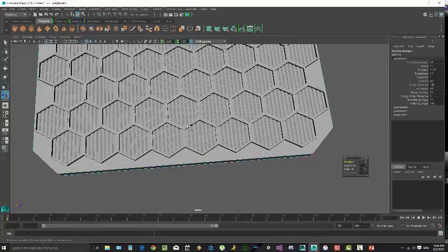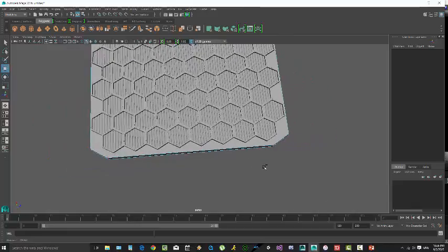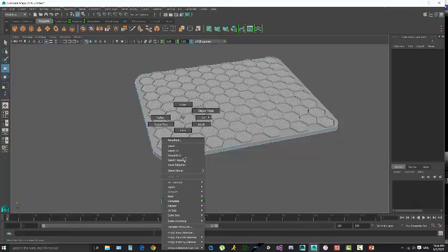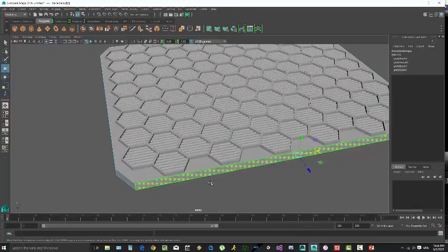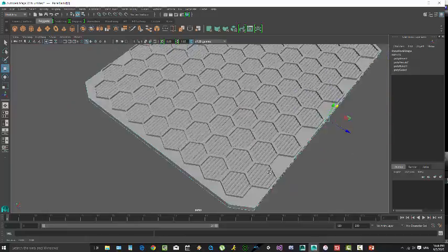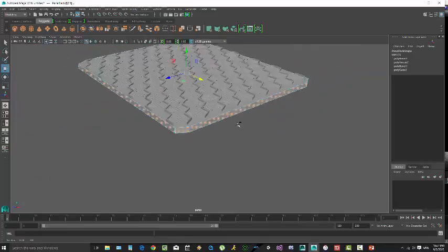Well, I'll select vertex, select this group of vertices, Shift and marquee select this group. Use my move tool so I make sure I move them both the same amount. Move it something like that. Doesn't look great, but that's fine. Right click, choose face, and we're going to add some more visual detail or some more visual interest to this. We're going to select this face and Shift, double click the next face in this ring.